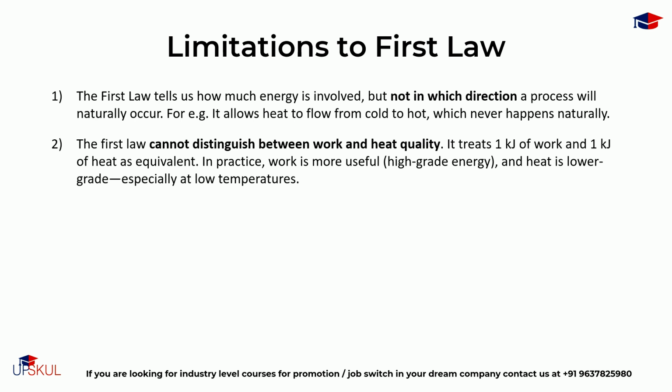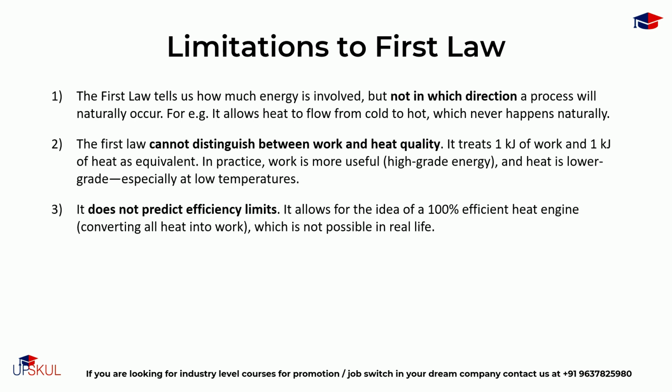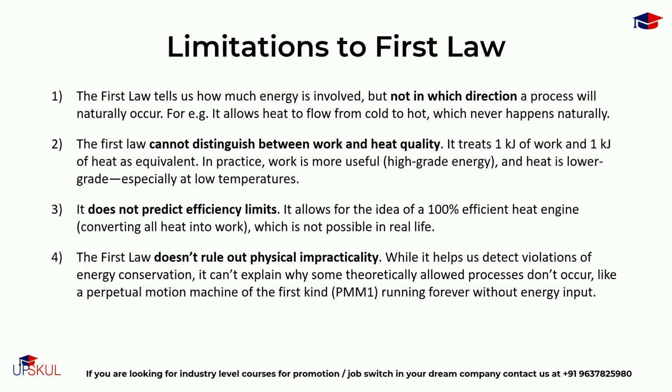The first law does not predict efficiency limits. It allows for the idea of a 100% efficient heat engine, that is, converting all the heat into work, which is not possible in real life. Then, the first law does not rule out any physical impracticalities.